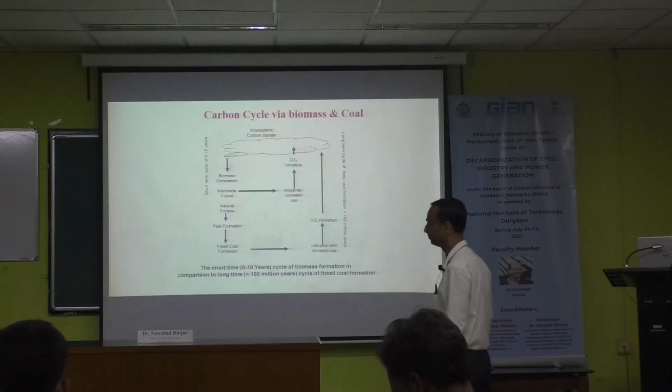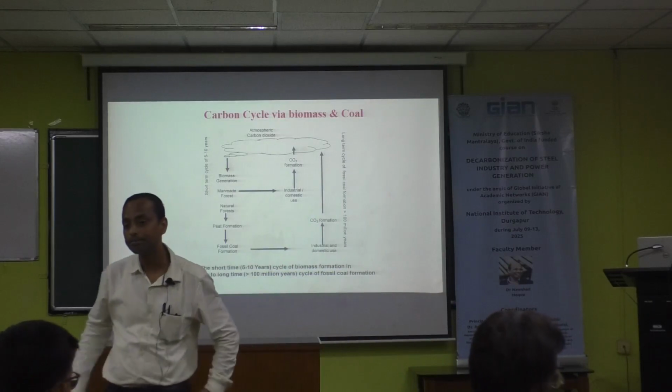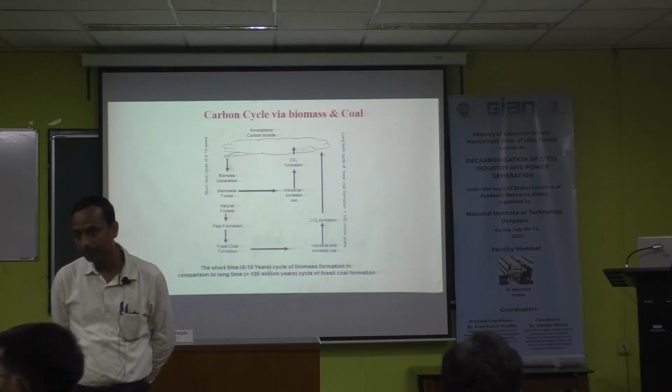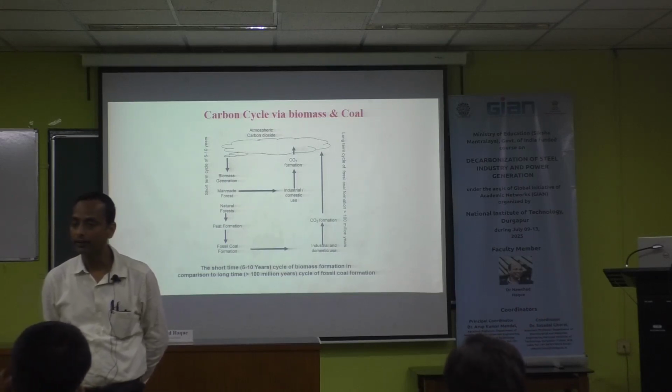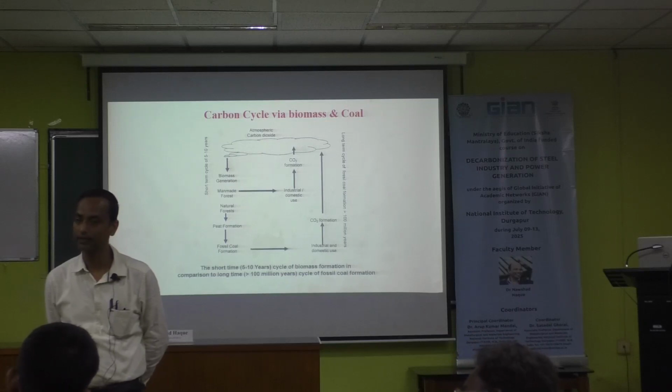So the increased Fe content in composite pellet is due to lime addition. As compared to iron ore pellets, the Fe content is around 62%, and in composite pellets the Fe content is 72 to 80%, I guess. That's slightly lower. Fe percentage in the composite pellets was about 72 to 80%. So the additional Fe is from lime.